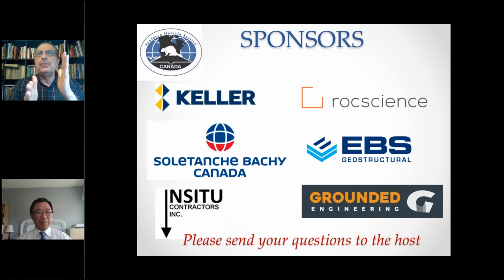The distance between the reference beam and the pile itself or the pile cap is not important because the reference beam is already above the ground. But the length of the reference beam is important. The supports that the reference beam is seated at, or supported with, these support points should be away from the pile. And usually it's asked to be more than 3 diameters in each direction.